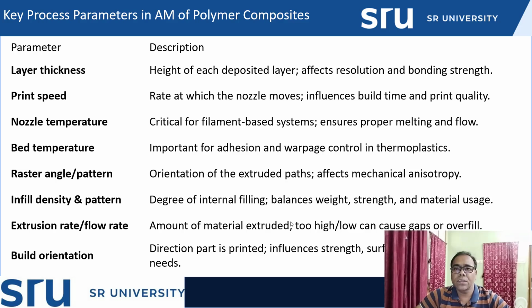So in that case, you have to ensure that whatever the maximum temperature the nozzle is achieving, the materials should also have a similar kind of melting temperature. Then only proper melting will take place and the deposition will take place.